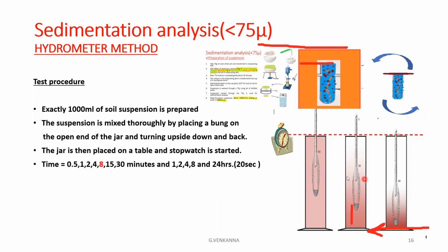Like this way, after the time taking process, the large particles settle at the bottom. Automatically the hydrometer goes deeper and deeper, and after 24 hours, again the large solid particles go deeper and deeper, and the hydrometer also goes deeper and deeper.